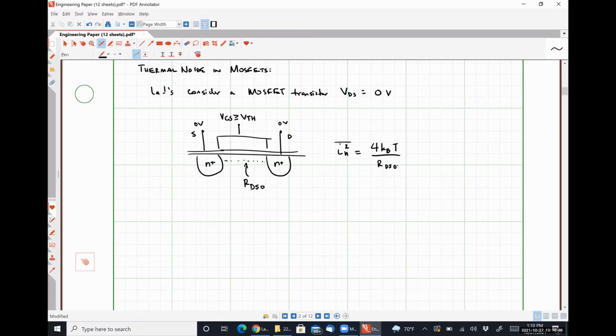and then we're going to see what happens when we apply bias voltages, right? So whenever the voltage present at the drain terminal is above the voltage present at the source terminal, what happens to the profile of our inversion layer? Tilts, right?